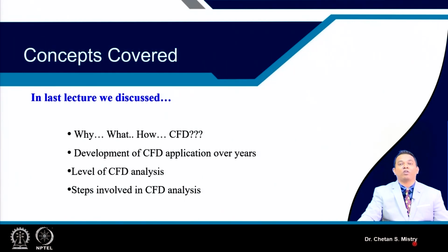Then, based on that study, the question is what exactly we are looking for. How is our flow behaving within the blade passage? Is it as per our expectation or not? That means we will be checking velocity components, flow angles, pressure distribution, total pressure distribution.